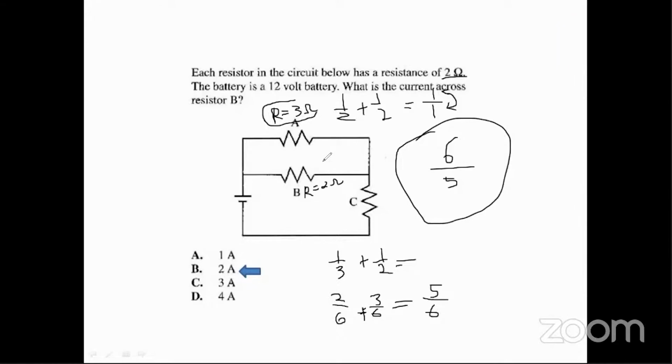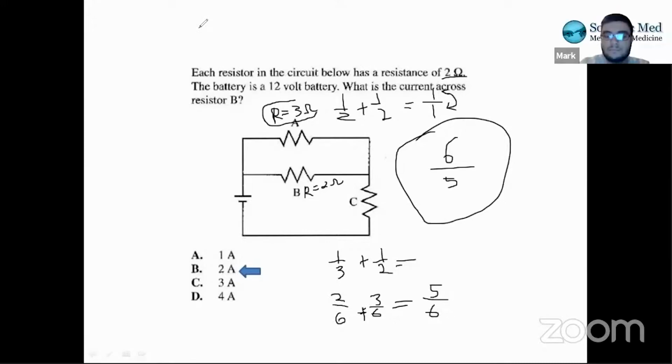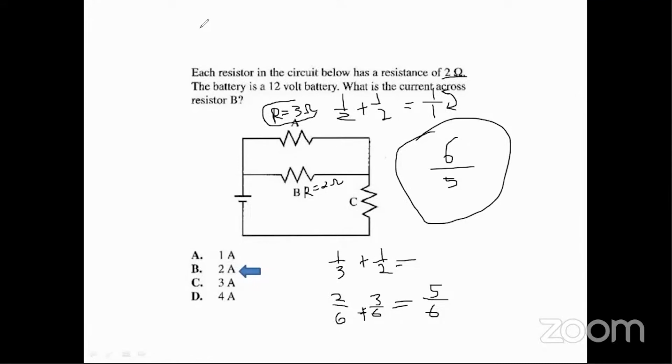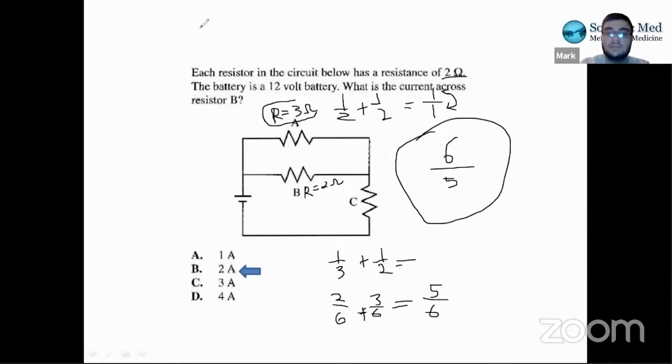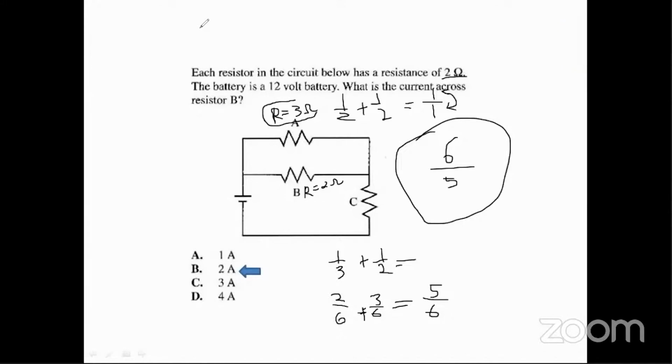I have a question. If it wasn't in series, we wouldn't have to split it. We'll just stop at V equals IR, and that will be the answer. If it was just in parallel. You noticed how you divided the current because it went from A to B. If it was just a series, it would just be one current, right? Yeah, if they were all in series, the current's the same everywhere. So you would just do four. The answer would be 4, right? Yeah, if they're all in series. Okay, thank you.